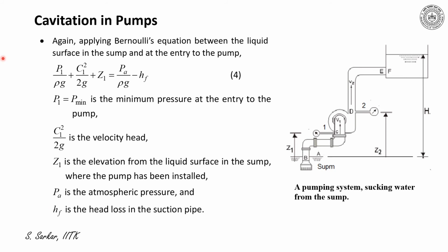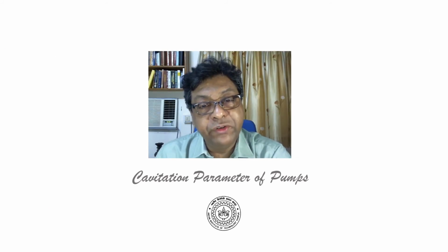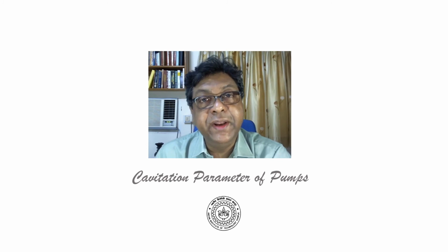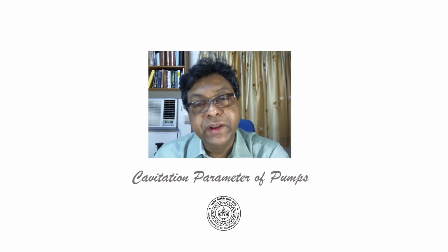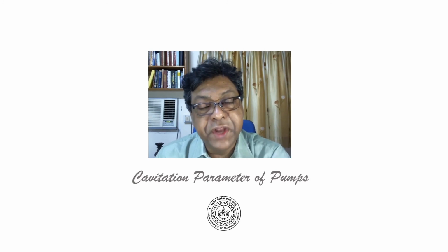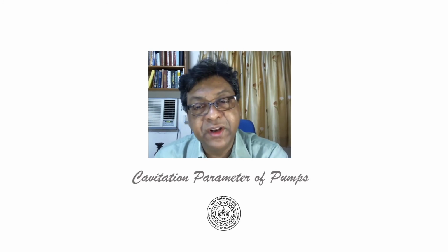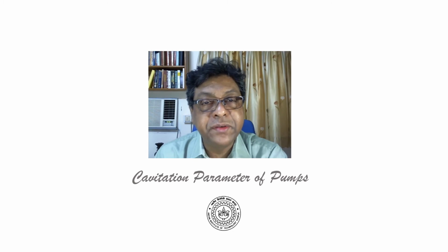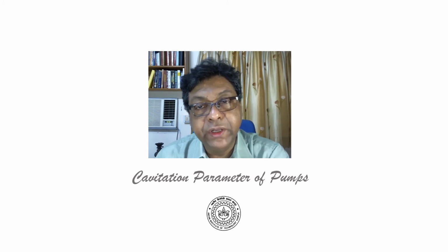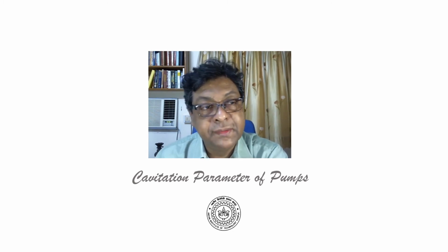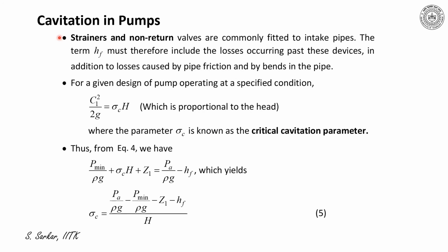Here, as before, I will define the critical cavitation parameter for a pump and NPSH, that is net positive suction head, as I had already defined for a turbine. Strainers and non-return valves are commonly fitted to the intake pipe.